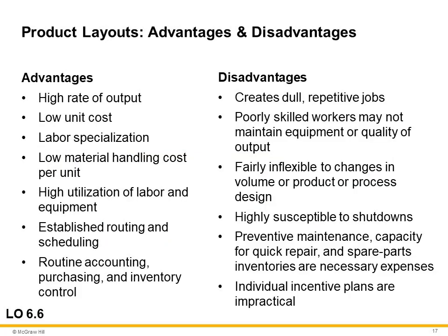There are advantages and disadvantages for product layout. I just mention a few of them. As an advantage, a higher rate of output. In other words, we have high speed in our production line in product layout. The second advantage is your total cost is lower compared to other layout types. As a disadvantage, you are not very flexible to market change or customer demand change.